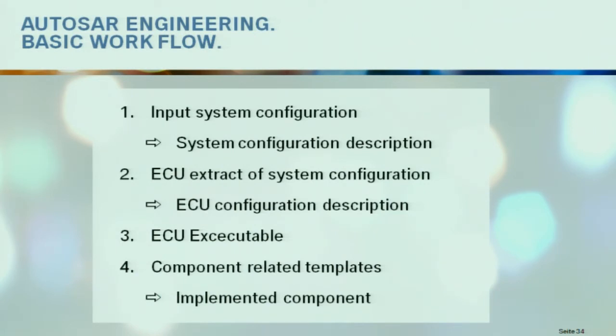So the basic workflow is: you have the system configuration, meaning all the software components needed in the system together with the communication between the software components. This is the system configuration description, and together with the set of control units, you get the ECU configuration, the control unit configuration.